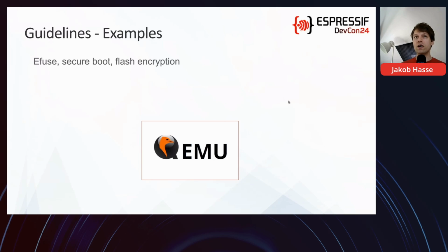So if you have, for example, 100 development cycles, or development, test and verify cycles, and you do that on the chip, then you just basically waste 100 chips. On the QEMU, that does not happen. You just run QEMU, and it resets the eFuses at the next reboot of QEMU, I think, or depending on the setting. And then finally, you should still verify your applications on the actual chip, but you will waste much fewer samples of ESP32 series chips.